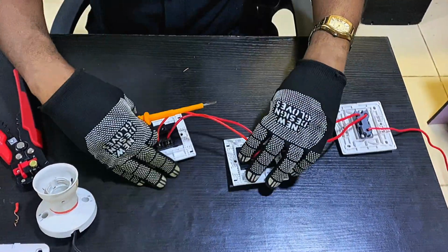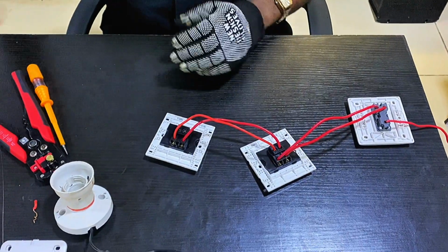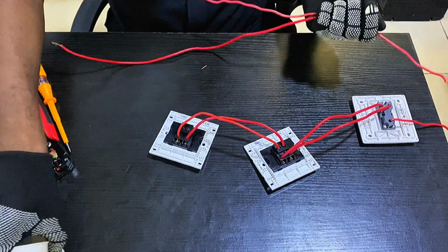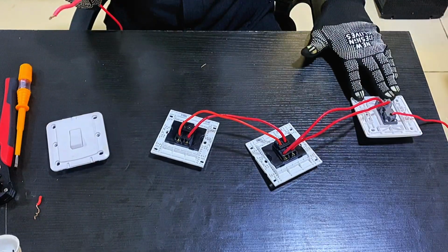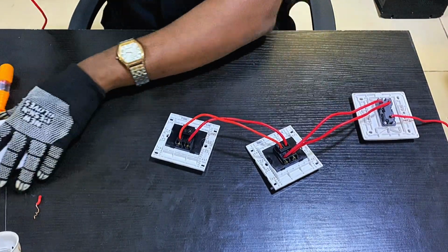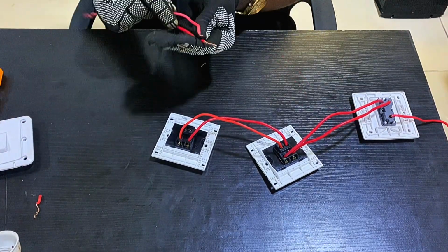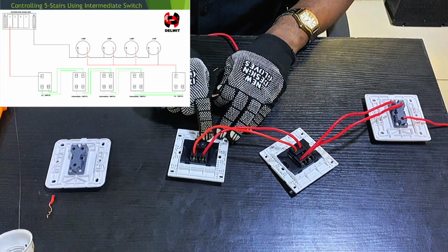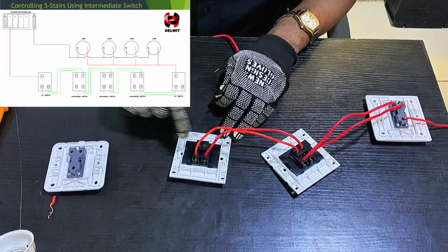All right, so you now take the last set of stripped cables that you are going to connect. This last set is going to go to the last floor. You can see now this is your ground floor, first floor, second floor. This is the last floor, the third floor. So you take these cables now, you connect 3 to L1, then 4 to L2.